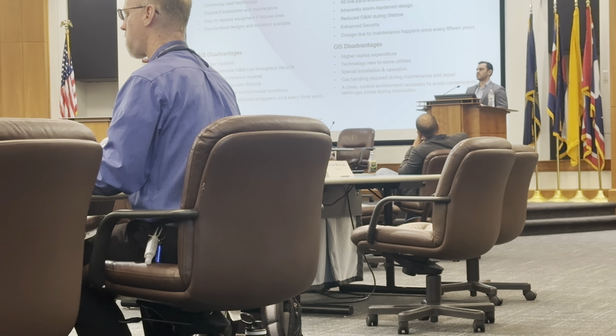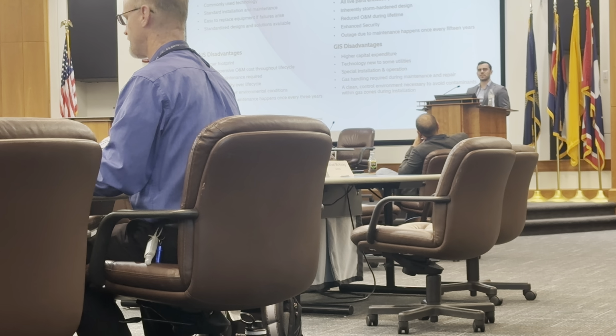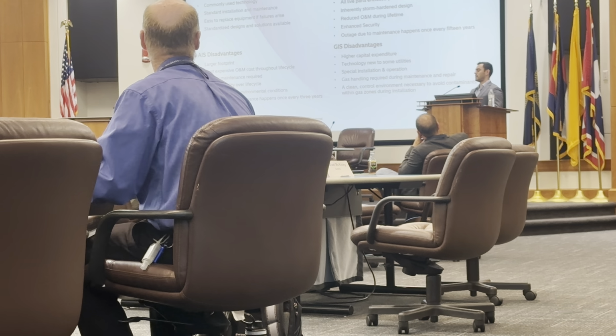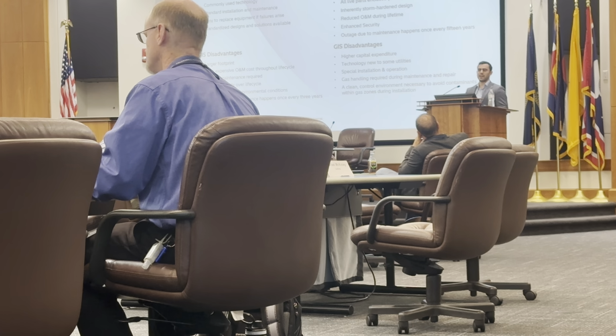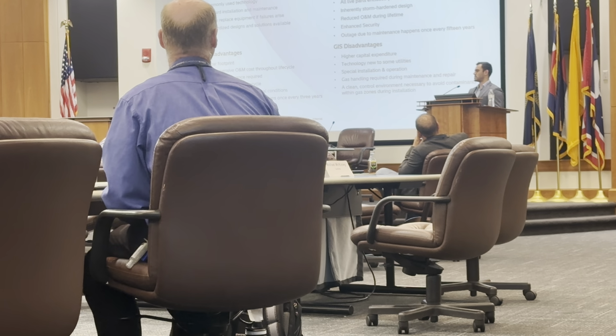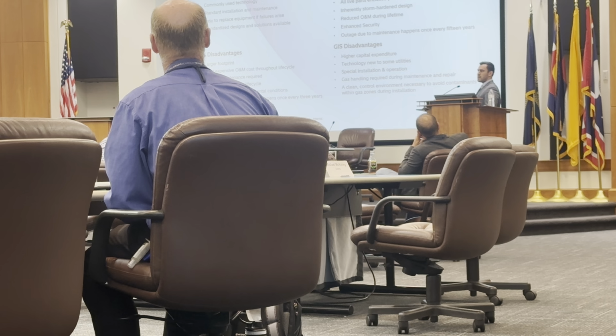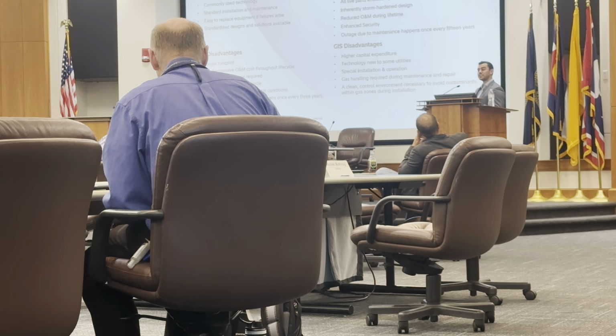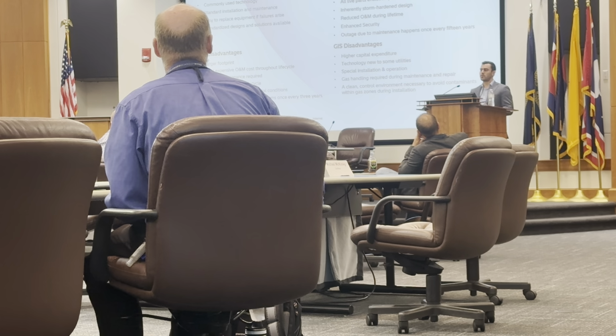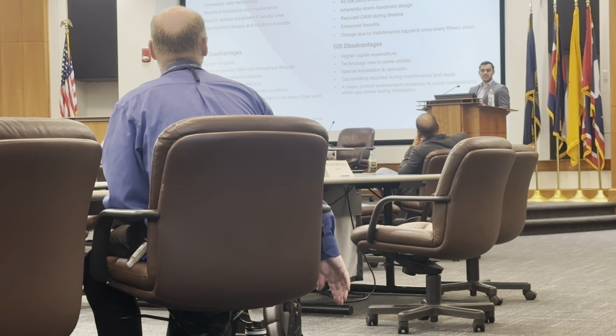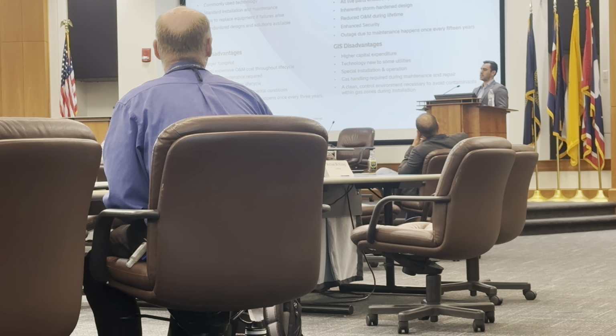Some disadvantages is, of course, the capital expenditure of the technology. The technology is new to a lot of utilities in the West Coast, in the East Coast, Northeast, Southeast, wherever there's a large plot of land. Most utilities haven't heard of what a GIS is. And some disadvantages: the gas handling required during maintenance and repair. That doesn't necessarily mean that you have to de-energize or remove the gas every single time you do maintenance, but maintenance does happen every couple of years.